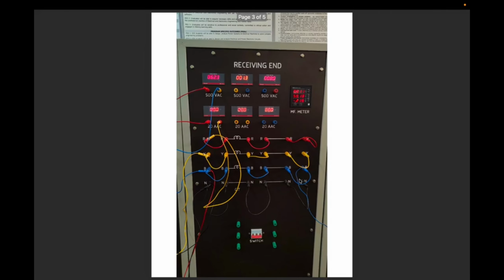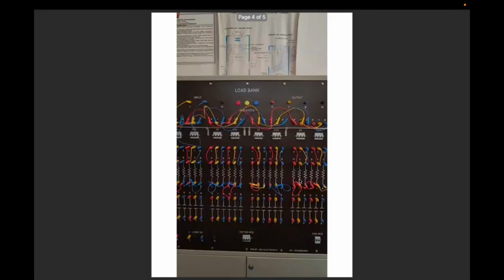For fault or stress creation, we can manually create abnormal conditions by increasing load, disconnecting the sections, creating overload, and simulating faults using this load bank. This helps us generate real-time stressed conditions.